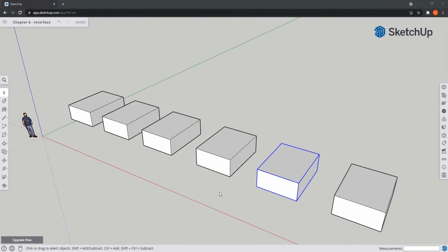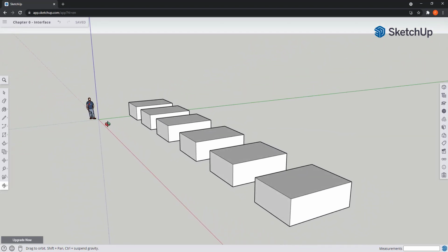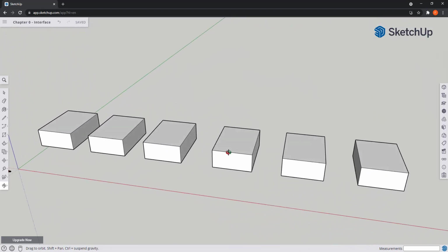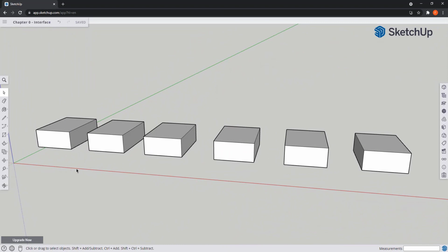As SketchUp Free is a 3D interface, as the 2D view is only available for the paid version, we will need to use the Orbit tool a lot. With the help of the mouse, it's pretty easy. We only need to click and hold the scroll wheel in order to activate it, then just move the pointer to rotate around the workspace.